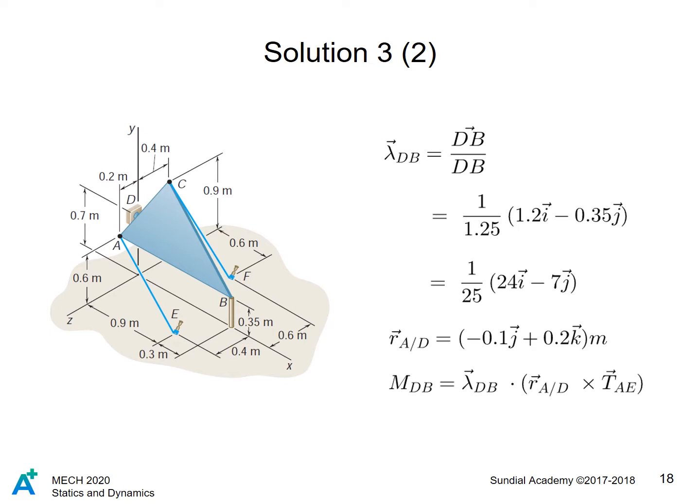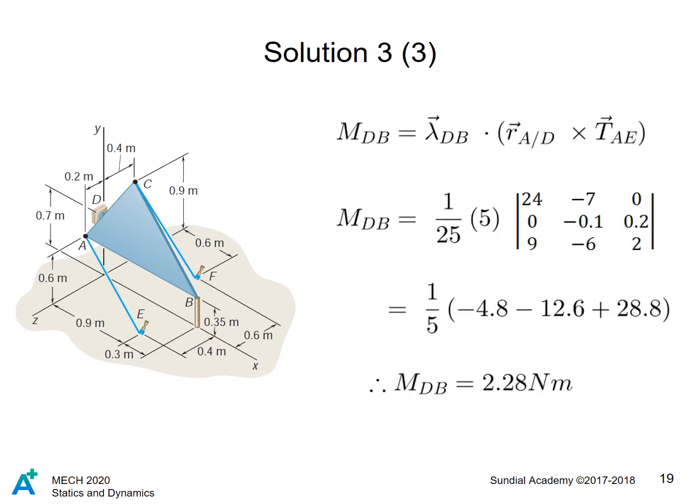times magnitude V2 times cosine theta, we see that to find the projection of the moment vector onto the modified axis vector, we need the unit vector of the modified axis. We perform the cross product operation with the radius and force vectors, then perform an additional dot product operation on the general moment axis with the unit vector of dB. Thus, we arrive at our answer here, which is the moment about dB.